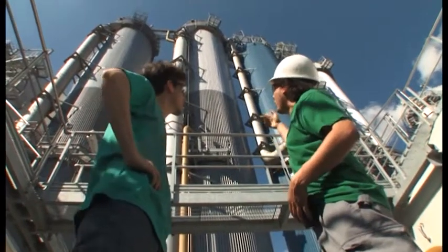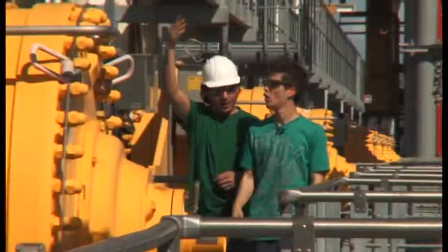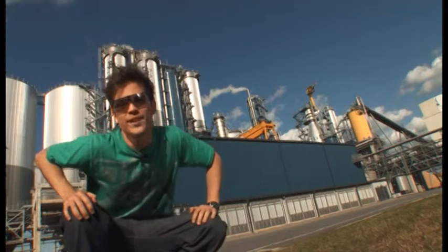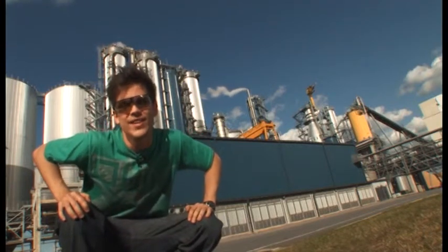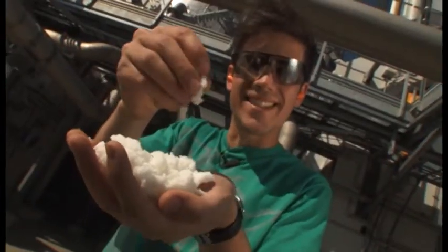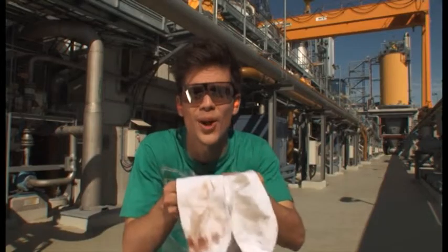The pulp goes through several bleaching stages where the lignin that still remains is removed. Several products are used for this purpose, where the main one is chlorine dioxide. Remember, this is a mill with minimum environmental impact, and that's why modern pulp mills don't use elementary chlorine anymore, but chlorine dioxide instead. Bleached pulp, ready for drying. It looks like cotton.